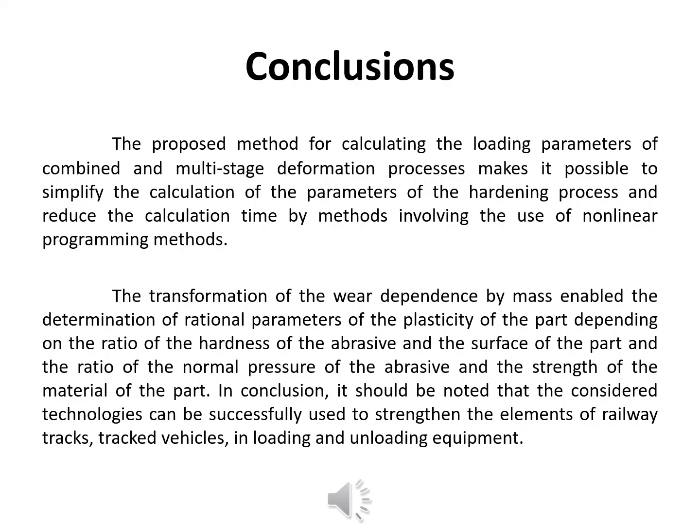The proposed method for calculating the loading parameters of combined and multi-stage deformation processes makes it possible to simplify the calculation of the parameters of the hardening process and reduce the calculation time compared to methods involving the use of nonlinear programming. The transformation of the wear dependence by mass enabled the determination of rational parameters of the plasticity of the part depending on the ratio of the hardness of the abrasive and the surface of the part and the ratio of the normal pressure of the abrasive and the strength of the material of the part.